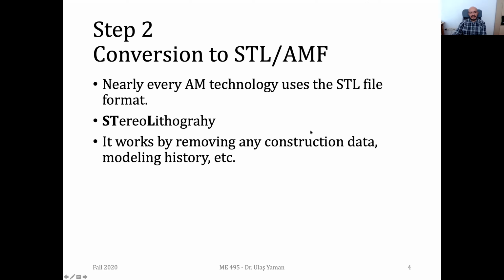And the problem is that in STL files, we only have the information of triangles, the vertices of the triangles and the normals of the triangles. So we don't have any information about the construction data, how we designed this part, or about the color, or the assembly. We only have information about the outer profile of the model.